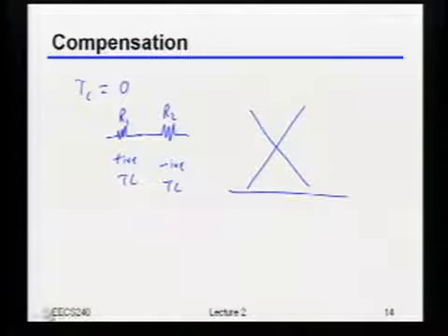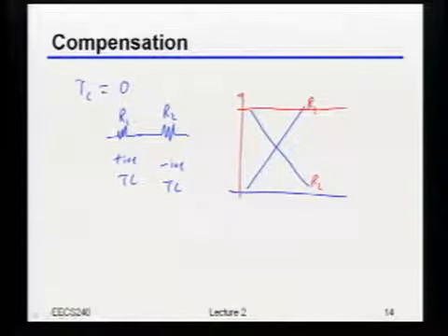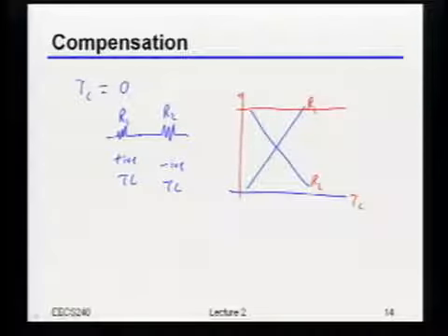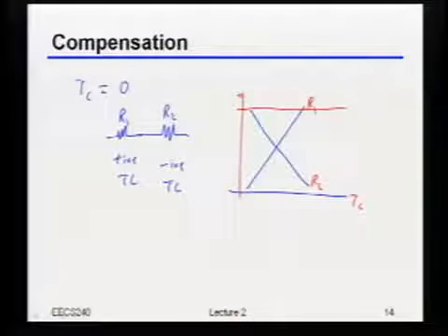So if I look at, maybe I'll do this in a different color just so it's clear. Let's say that's the R1, let's say that's the R2, so that the total resistance does something like that versus temperature, right? So it's exactly what you said. If I knew what those temperature coefficients were, in principle, I could build something that would actually cancel those two things out. And in fact, obviously, you could try and do the same thing with the voltage dependence as well, right?